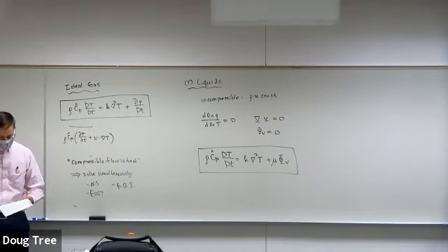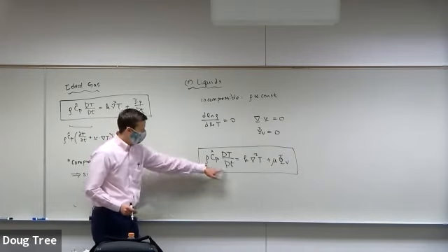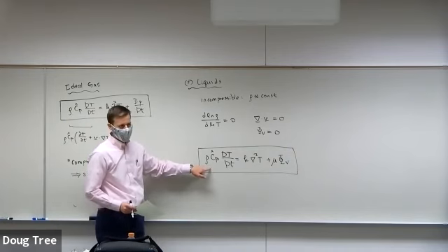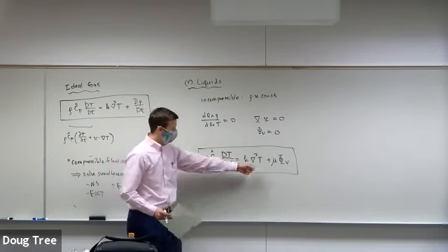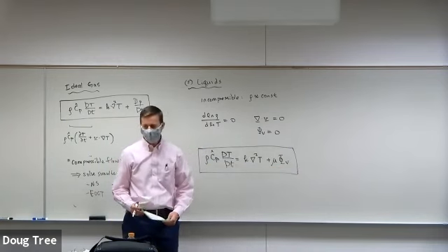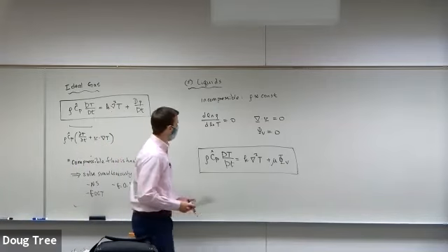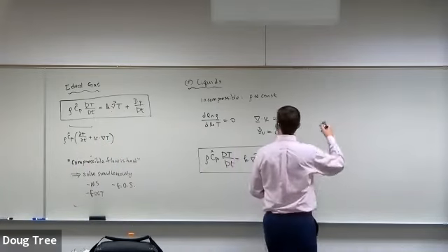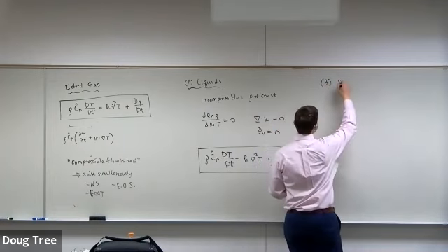Okay, so now in this case, I've still got the convected derivative, the material derivative over here, right? Rate of change that depends on both time and space, thermal diffusion, and now I have viscous dissipation from shear, but nothing from expansion or contraction. Okay, so liquids are yet easier. And finally, the easiest one are solids.